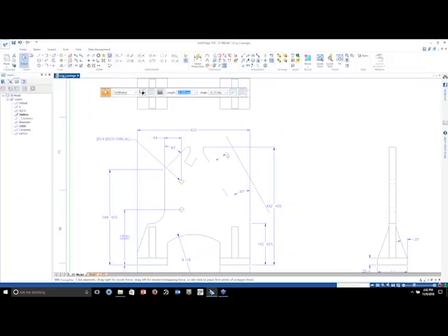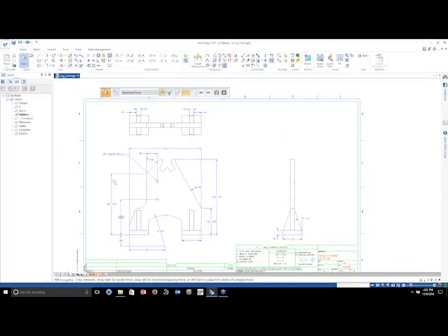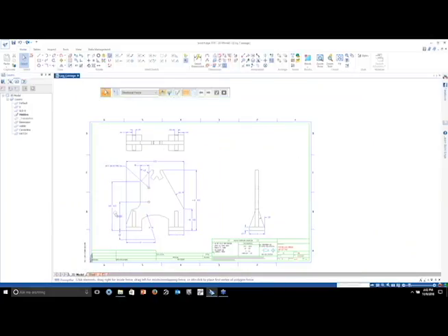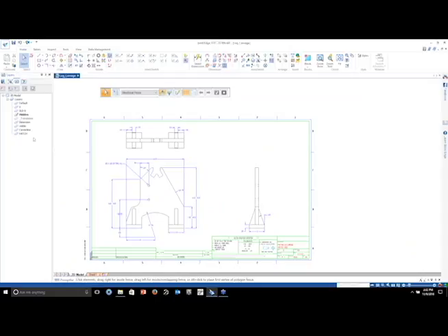All right, here we have it. So here's the 2D sketch geometry, and it's just 2D sketches. You notice I can just grab a line and kind of just pull them apart. So they're just sketches on a 2D sheet. First thing I want to do is I only want this drawing geometry, but there's a lot of stuff in the way, some notes and stuff I don't need, some hatching I can turn off.